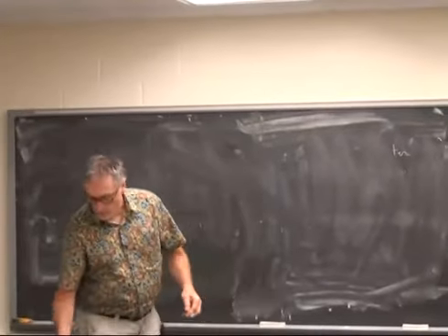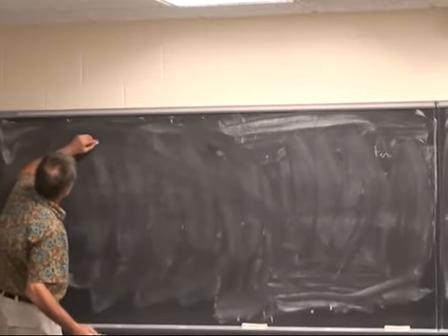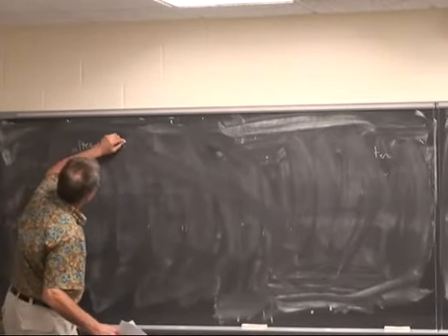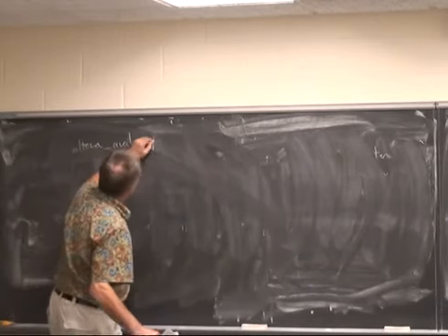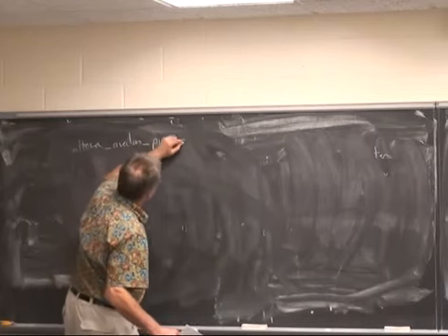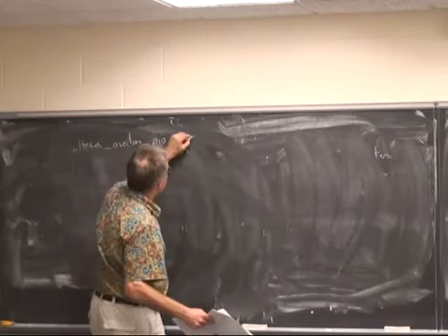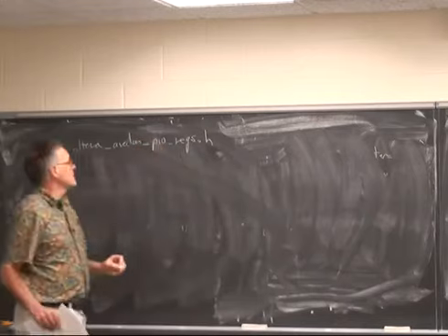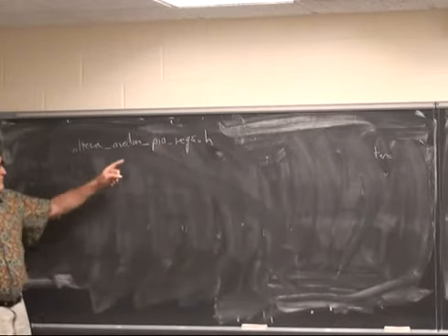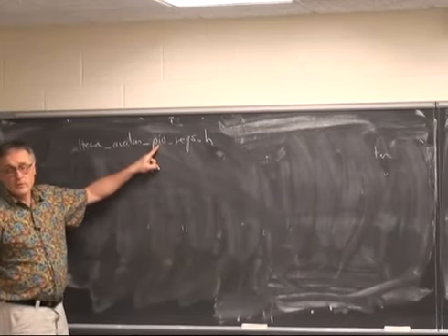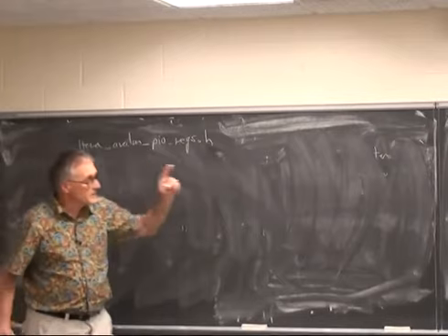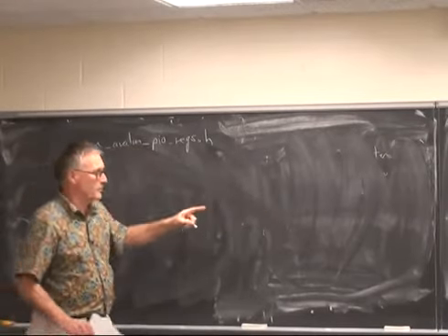You can go up one level. If you look at Altera_Avalon_PIO_regs.h, you will find macros that define how to get to all of the parallel I/O ports, all of the parallel I/O port status, or all the parallel I/O port register block.